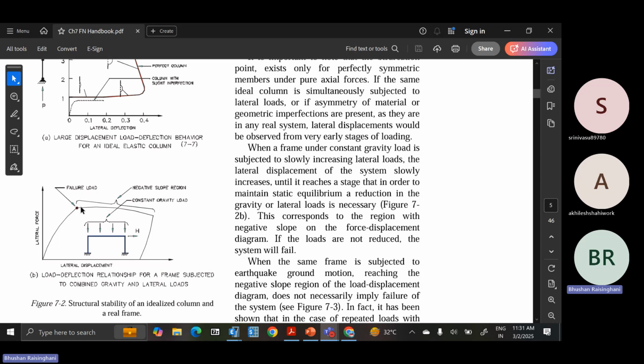So that we are representing also ductility. So delta ultimate upon delta yield. So the more this ratio is, the more inelastic deformations it can resist and be stable and intact during the earthquake.